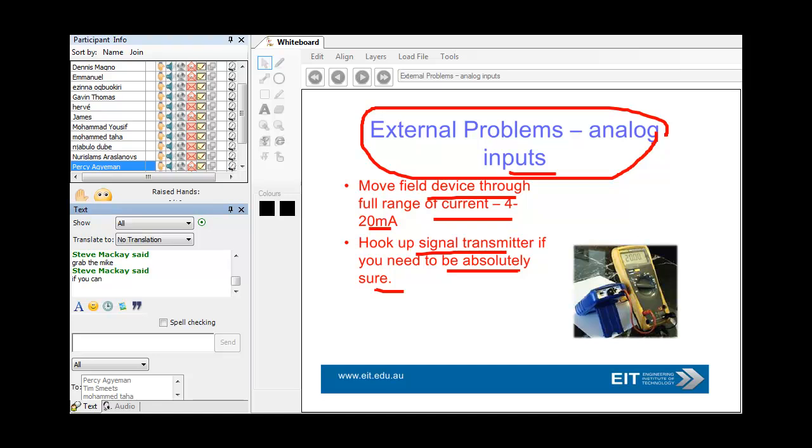So you take your analog inputs, apply your PID algorithm, which is proportional integral, a simple flow loop, and then you drive the output. And I couldn't get the loop tuned. I battled. I checked the PID parameters, did everything. And basically, what I was reading with my analog input was absolute rubbish.